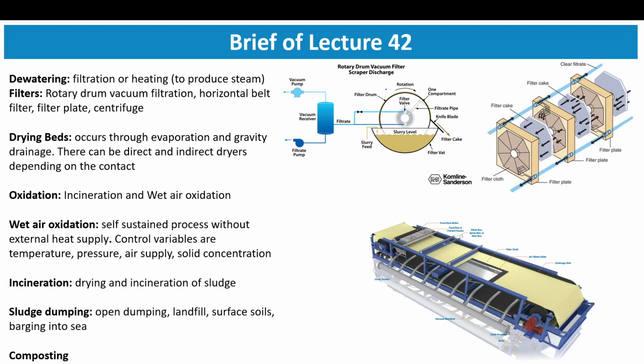First is the rotary vacuum filter, where this is the drum, and here there will be a filter attached. Now when it passes through this slurry, on applying some pressure difference, some vacuum is generated inside, which will cause the liquid or water to pass through this.